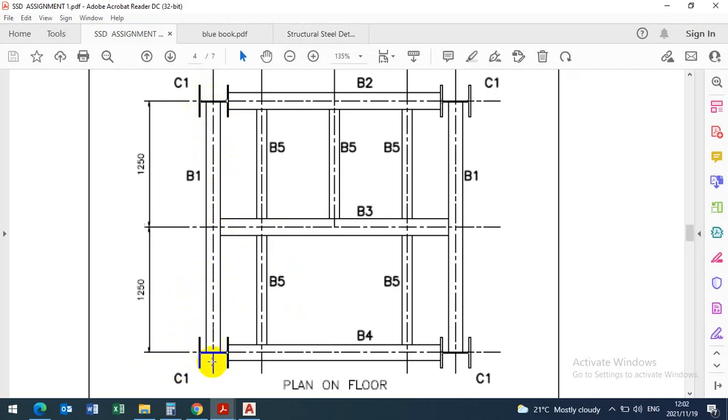And here you need to do detail of the end plate. So you're going to have 1, 2 end plate details, and here only the hole positions in the web of beam 1. And these hole positions will be based on the hole positions that beam 3 will come with on its end plate or on its angle cleat. That's how you're going to locate the hole positions in beam 1, based on the end cleat or end plate that you are going to use.